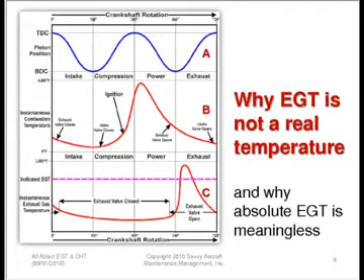It sees exhaust gas which starts out very, very hot, not anywhere near as hot as the peak in the combustion chamber. That's up around 4,000 degrees Fahrenheit. But it sees a pulse of gas that starts off quite hot, somewhere close to 2,000 degrees. But then as the exhaust stroke continues and the pressure goes down and this gas is being allowed to escape from the combustion chamber, it cools down very, very rapidly.